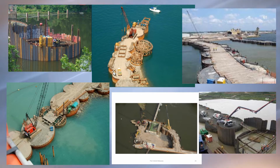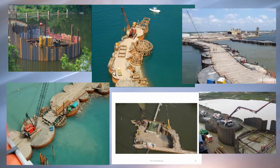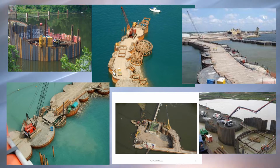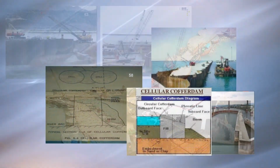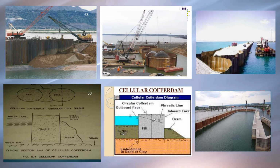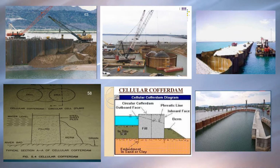This type has the advantage that each cell may be filled completely to the top before starting the construction of the next cell without causing any distortion to the shell of the cofferdam. Once a cell is completely filled up, it can be used for the construction of other cells. Each cell acts as a self-supporting independent unit.